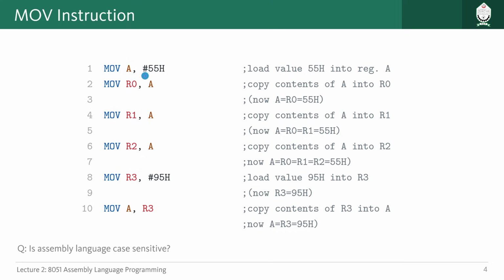By using this hashtag, we are saying that this hexadecimal value should be moved or stored onto register A. Instead of moving data from one register to another, we are directly using a value and putting it onto a particular register. So that is the idea. Whenever we use this hashtag, it becomes a value.